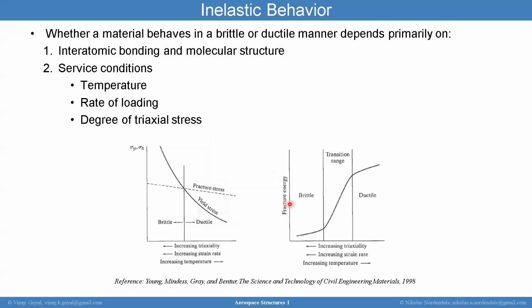So that's huge. That's huge because it's telling us that whether a material behaves brittle or ductile can also depend on the stress states and how quickly you load something up. You can think that a particular metal behaves very ductile based on a uniaxial test, but perhaps it could behave quite brittle when you have a more complicated state of stress, right?